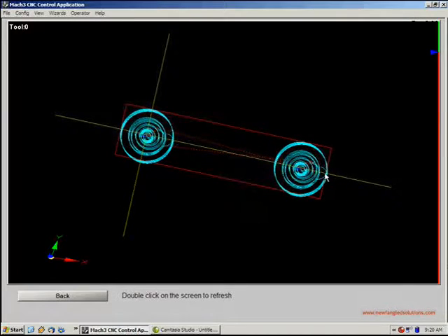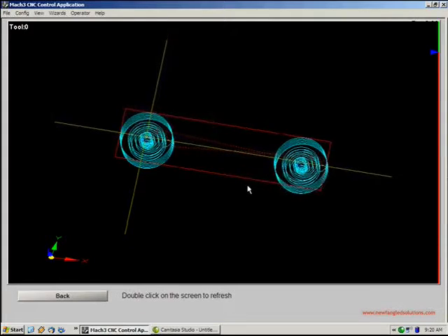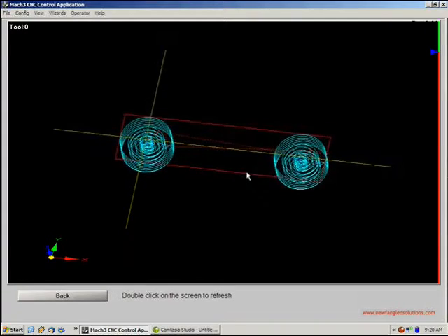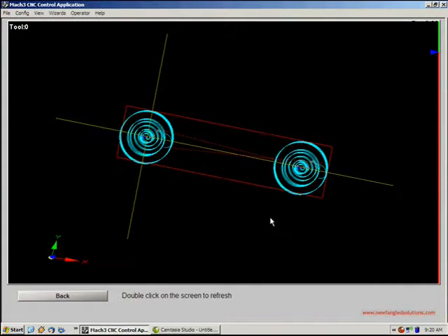You may look at this and say, wow, that's an awful lot of material that we're going to take away. This is actually the new compensation that's done inside of Mach3, the advanced comp. There's a G-code that is set in the beginning that sets your machine to advanced comp whenever you run one of the newfangled wizards. We did this because it's a little bit better compensation routine, and it gives you the opportunity to tweak the size of a pocket without reposting the program by adjusting a P parameter. This P parameter will be right on the line before it starts cutting, so it would be like a G41 P and the radius of the tool. As you adjust that radius, you can adjust the diameter of your part.